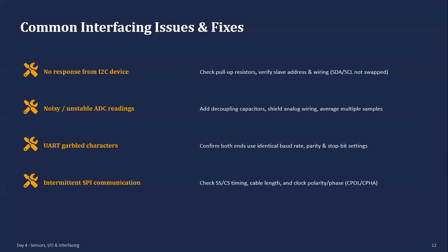So what are the common interfacing problems in the signal conditioning mechanism with the help of the sensors? During implementation, engineers often encounter common communication issues. If an I2C device does not respond, verify the wiring, slave address, and pull-up resistors.